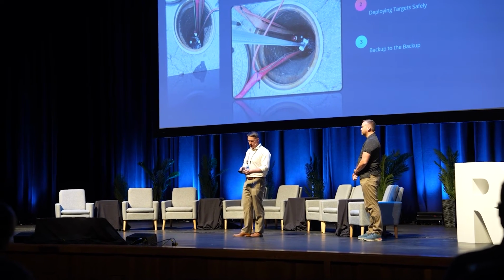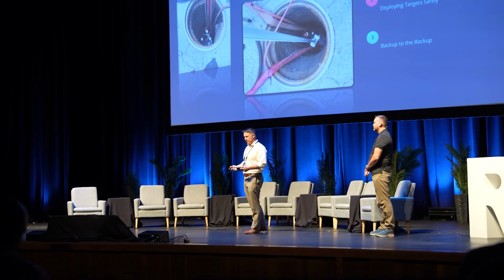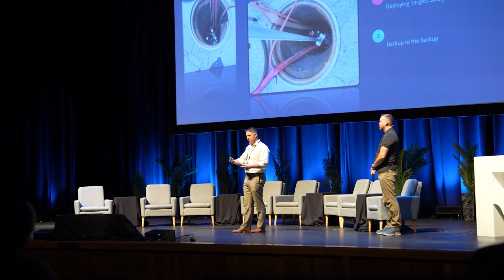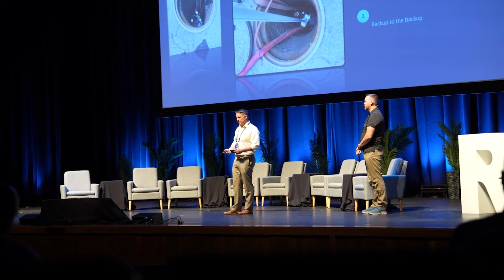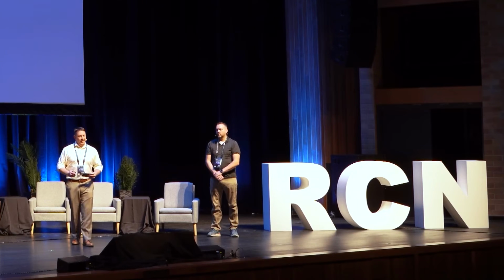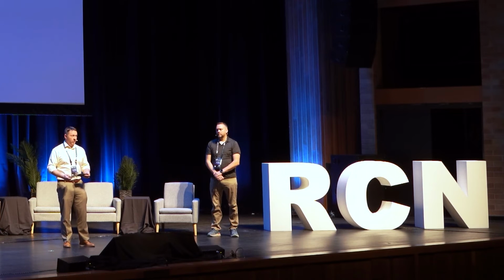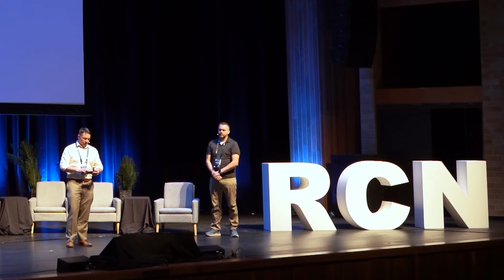And then we also used a Theta X 360-degree video camera, which we put on the end of a prism pole and ran down into the hole. We didn't even have to rotate that one because it takes a 360-degree video, and that was worth a lot in terms of what we needed to get for the client to further analyze and help them figure out what to do next.